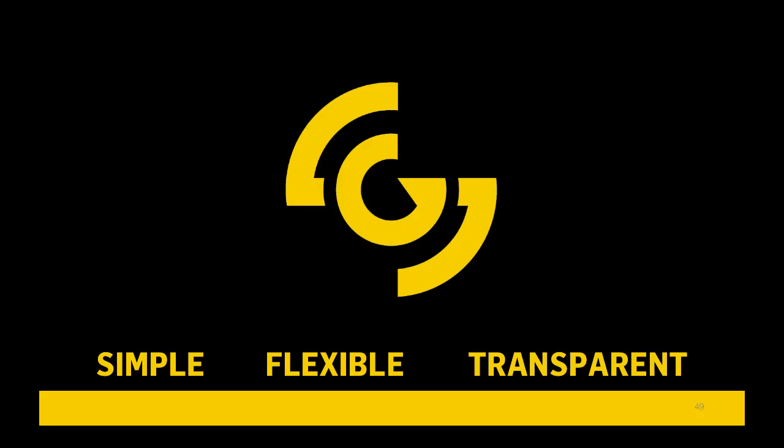One thing you need to be careful of is if you have the camera on the side of a roundabout, that makes it very difficult for tracking. If you can put the camera in the center of the roundabout, and, depending on the size of the roundabout, get up around 40 feet, that gives us a really good view of the entire roundabout, and we can work really well in that scenario.